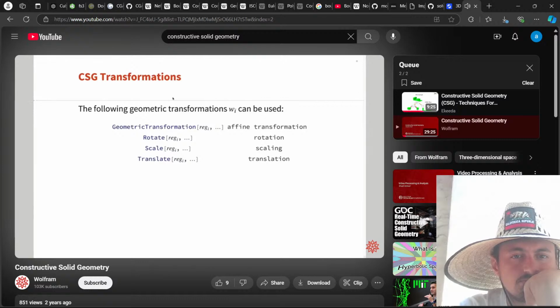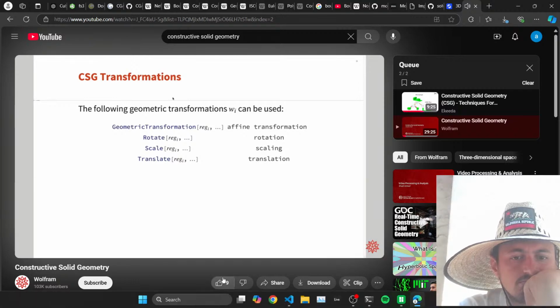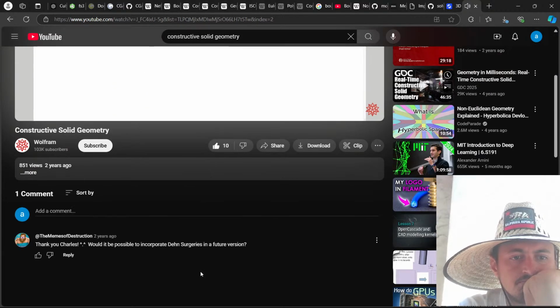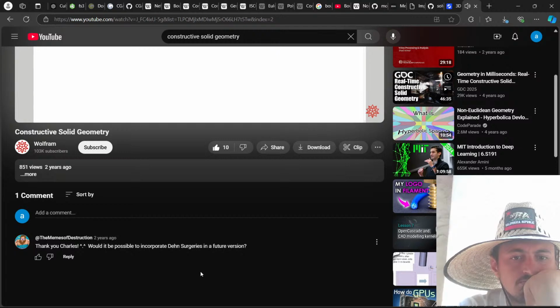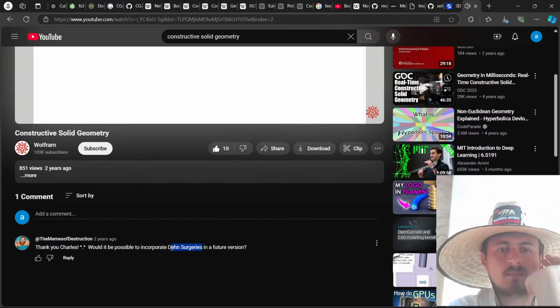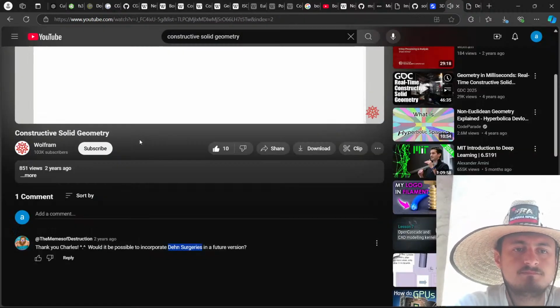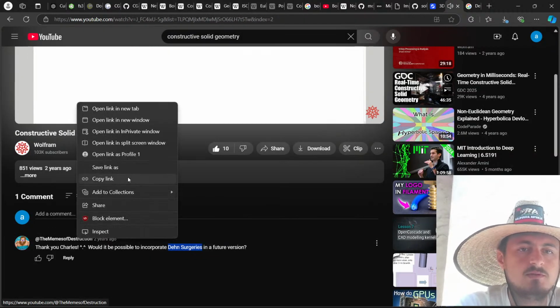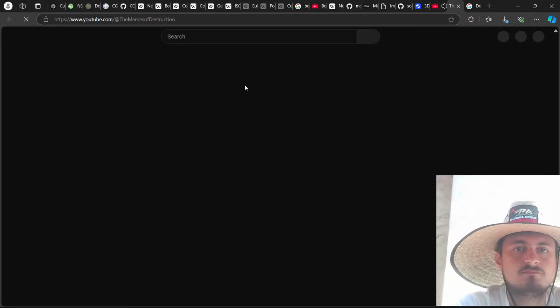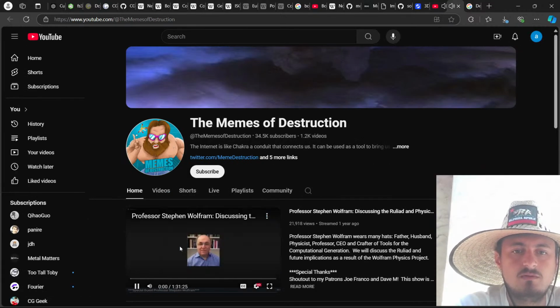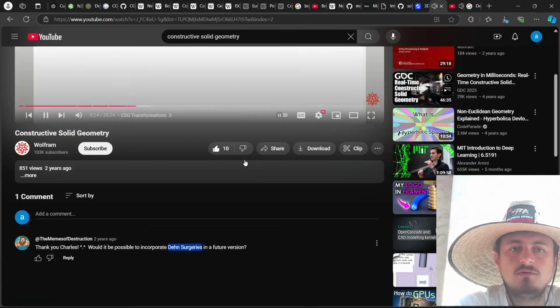And in terms of transformation, as I told you, for CSG, constructive solid geometry, usually you want to preserve that physical fidelity. So you restrict yourself to a set of geometric transformations, which are pretty much affine transformations. Essentially the set of transformations will preserve orientation as well as isometry, pretty much. This is scale and such. But you pretty much don't want to deform your object. You start with a rigid object and at the end get a rigid object. So in this case, we support translation, scale, rotation, and geometric transforms, where you can specify them.